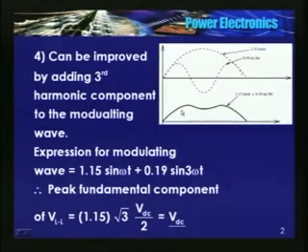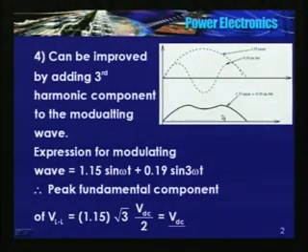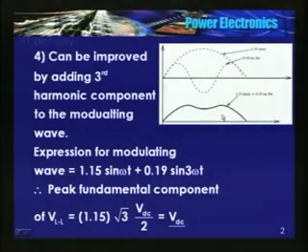So in this new modulating wave, there is no peak which appears in a sine wave. The area is improved here, okay. But then if you see the harmonic spectrum of the line to line voltage, there is no third harmonic. What did we achieve by adding a third harmonic component to the modulating wave?